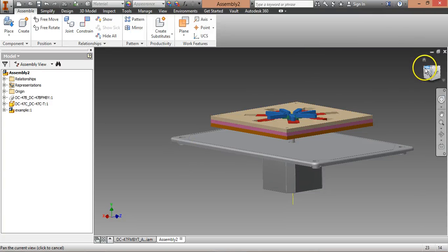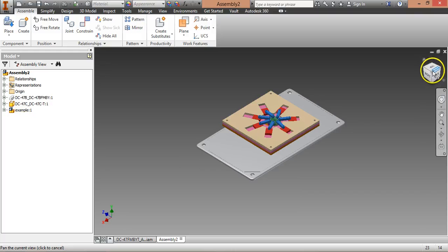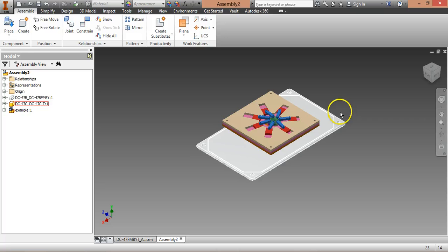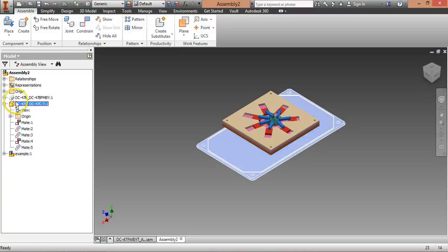So now the next step is to get all of the mounting holes for the motors, the stepper motor, as well as the rotary motor model. So the way we do this is by actually using the project geometry tool. This will allow us to, without measuring, place holes for the mounting components fairly easily.